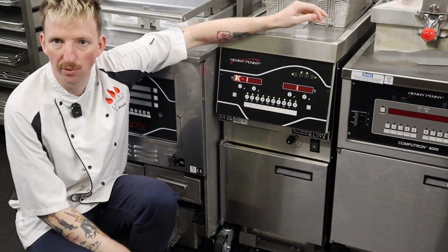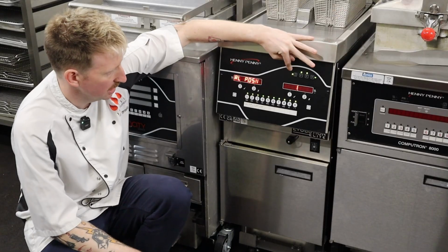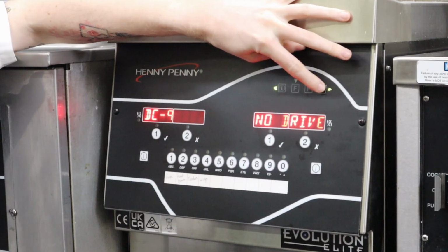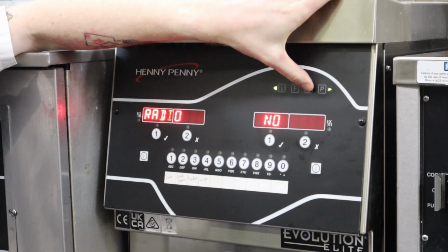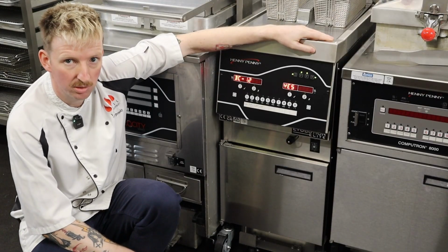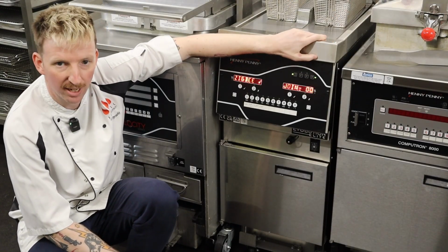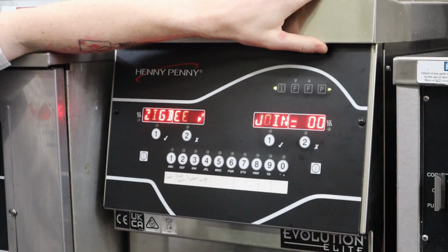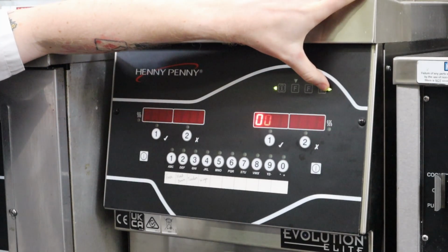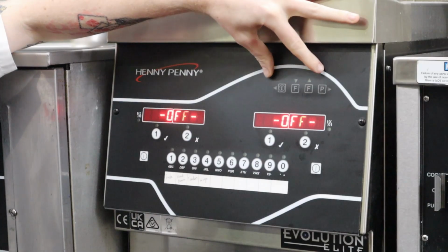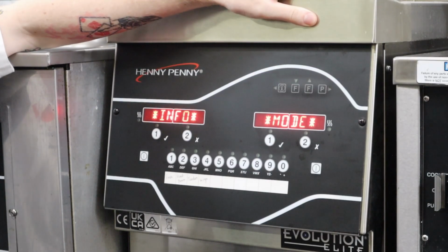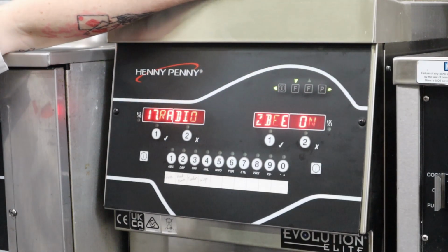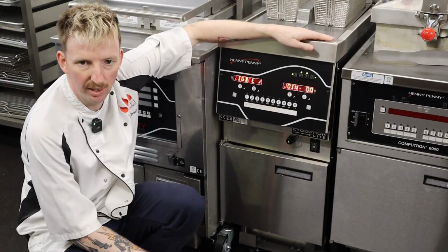And then we're going to scroll through our parameters in our data comms using the left and right arrows. We want to go to datacom 12 to make sure datacom 12 is set to yes, radio enabled. We can then directly see our radio info panel. You can get to this through the info mode as well. So if we come out of here by pressing and holding P, and then using I and P together, getting into info mode, I can then use my left and right arrows again to go over to my radio panel there. So we're in our radio info screen here.